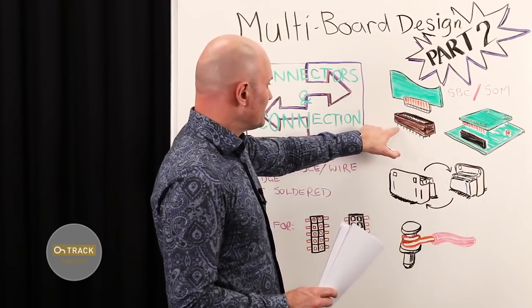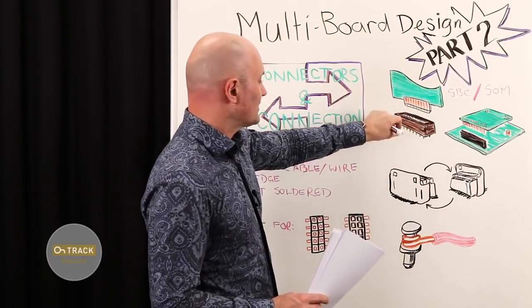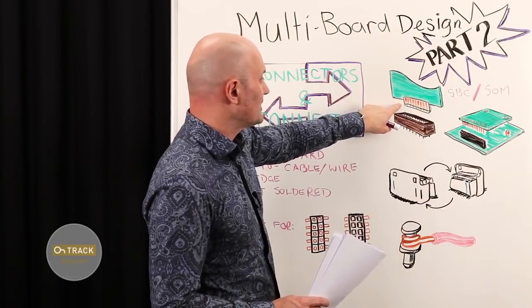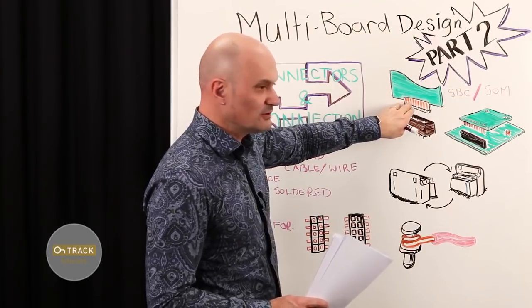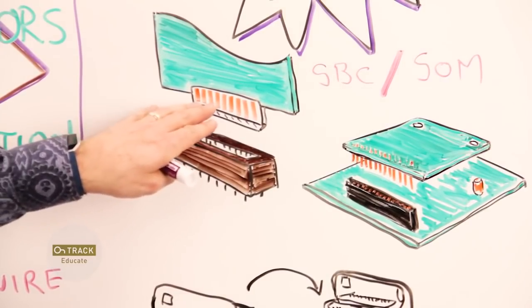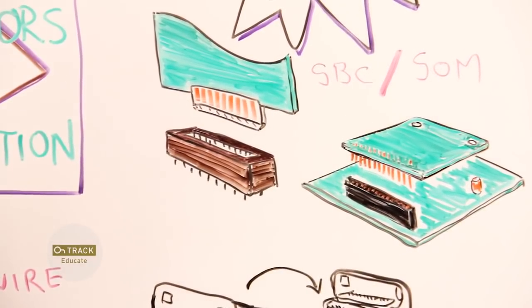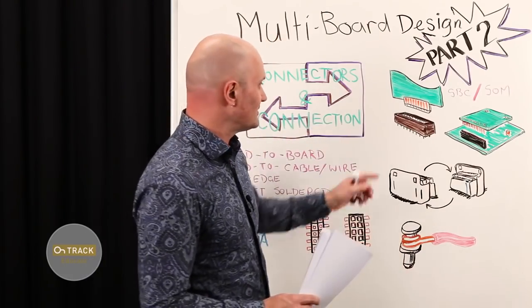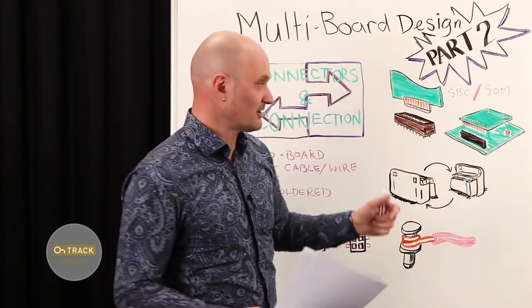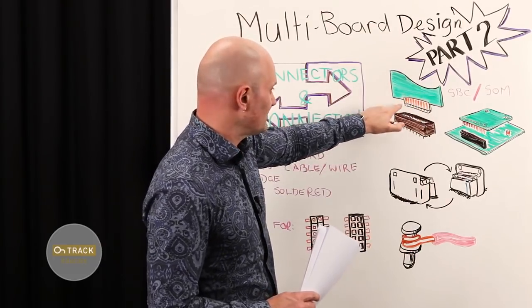But something to look out for here is these products may be in storage for some time before they're actually inserted. And so there's a design for manufacturing issue here where the actual printed circuit board, while you could use bare copper contacts, usually the standards require that you have hard gold plating on your contacts on the board edge connector. So we call these the gold fingers. So that adds a little bit of cost to your actual PCB fabrication, but it may be less than the cost of what would otherwise be a connector anyway. But it just means you have to specify a little more in your manufacturing documentation what you expect here.